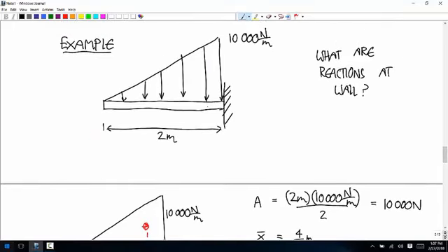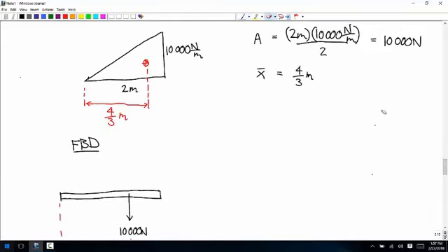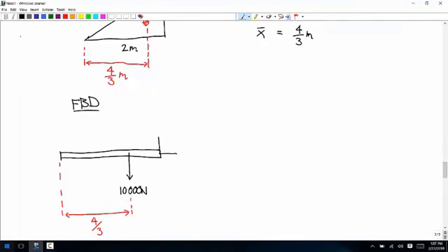So with a fixed joint like this, what are the reactions? That's right. This is in 2D. A fixed joint doesn't allow any degrees of freedom. So you need 2 components of force and 1 component of couple. Okay, so we have an unknown force vector. I'll call that R. And we have an unknown couple. I'll call that reaction moment, MR.